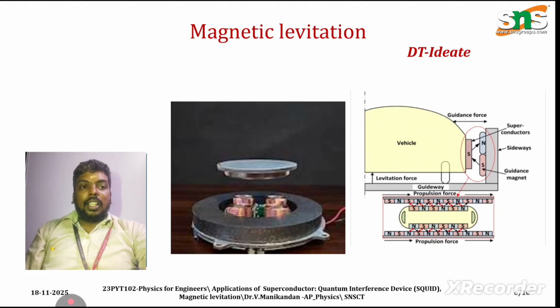A U-shaped guideway protects it, and the train is suspended about 10 mm over the air. So the train is frictionless and can reach maximum speed. Repulsion and propulsion are produced by these electromagnets, the supermagnets. We can change the polarity of the magnets to propel, accelerate, or reduce the speed of the train according to the input voltage. The supermagnets are controlled by current, so we can increase or reduce the speed of the train.